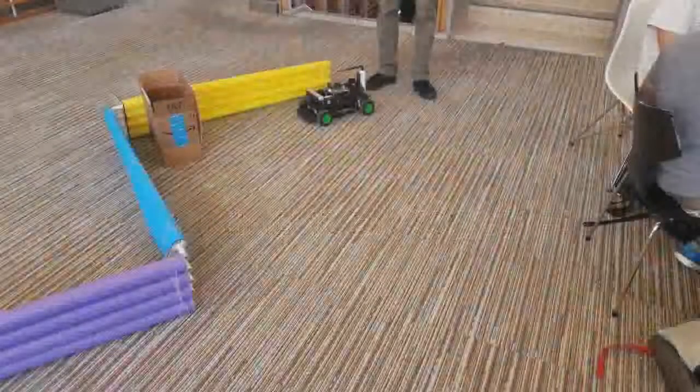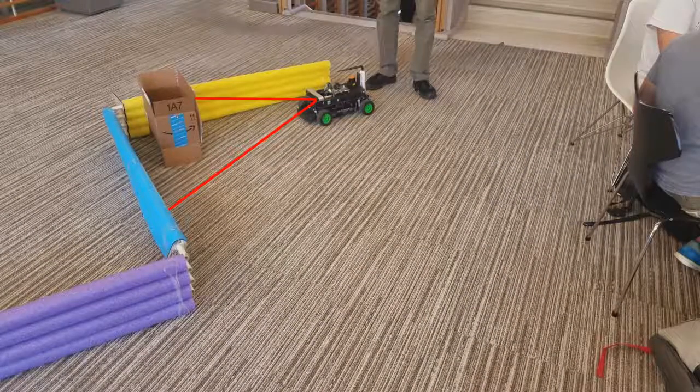At this point, the vehicle sees the red dot through the ZED camera, and the LiDAR returns a value from the front distance that is more than 1.25 meters. So the controller then decides to choose the state where it has to turn left.